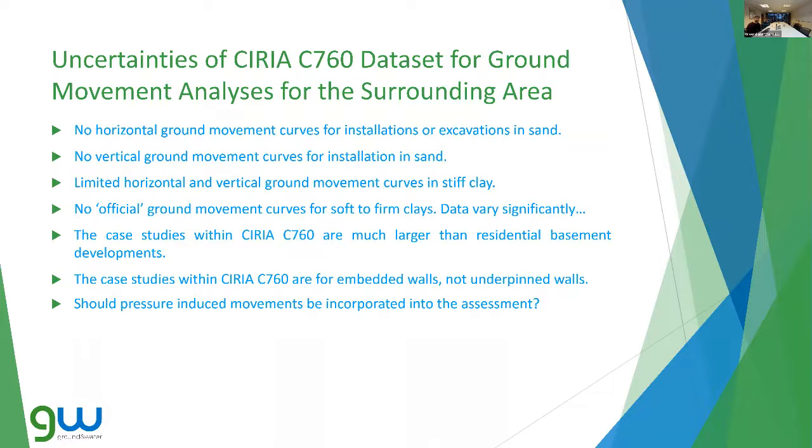There are no vertical ground movement curves for installations in sand. There are limited horizontal and vertical ground movement curves in stiff clay. And there isn't an official ground movement curve at all for installation, horizontal or vertical excavation for softer clays. Therefore the data does vary significantly, and the way that the ground is displaced and settles away from basements and installation of basements varies a lot between sands and clays and different densities.